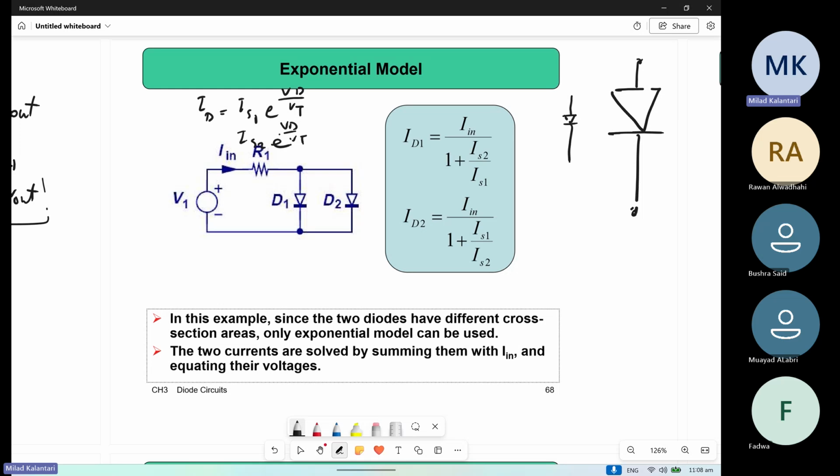The diode is similar. They all function similarly as diodes, but the smaller one may not carry too much current. The bigger one can carry more current. And in order to increase the current handling capability, you try to parallel these things, to increase the overall current capability of the circuit.